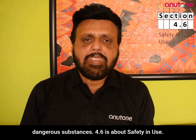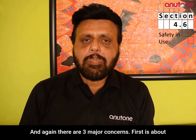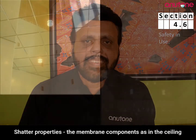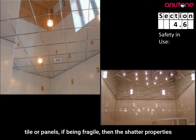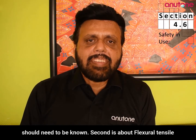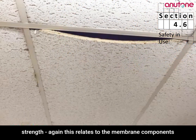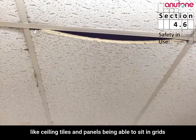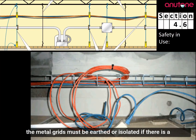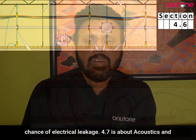4.6 is about safety in use, and again there are 3 major concerns. First is about shatter properties. The membrane components, as in the ceiling tiles or panels, if being fragile, then the shatter properties need to be known. Second is about flexural tensile strength. Again, this relates to the membrane components like ceiling tiles and panels being able to sit in grids within their self-weight. Third is about electrical concerns. The metal grids must be earthed or isolated if there is a chance of electrical leakage.